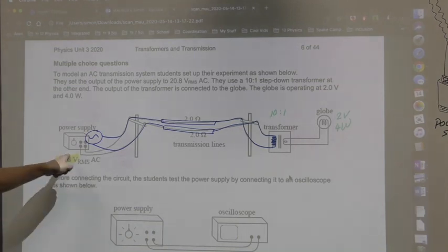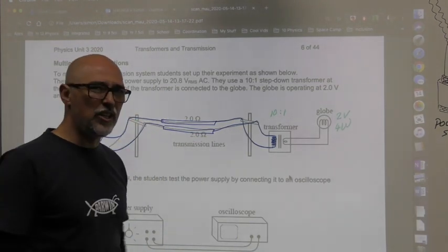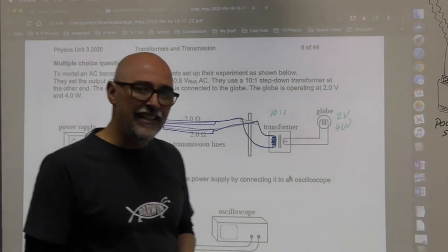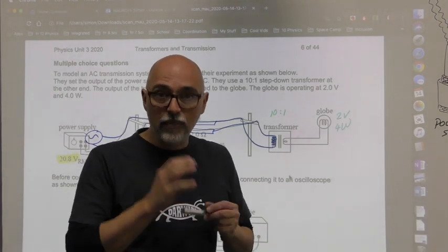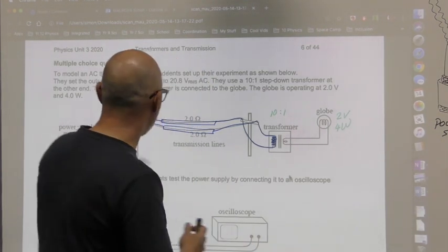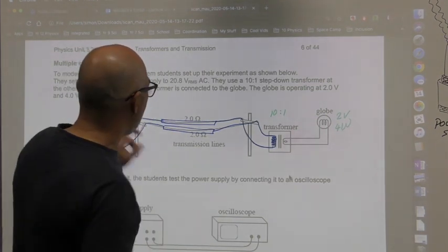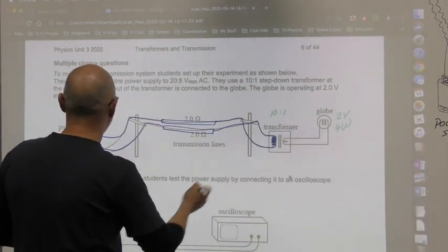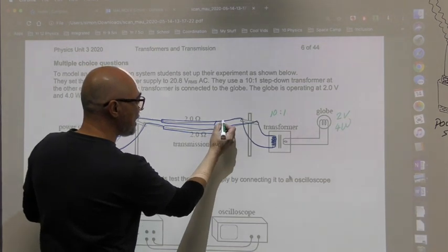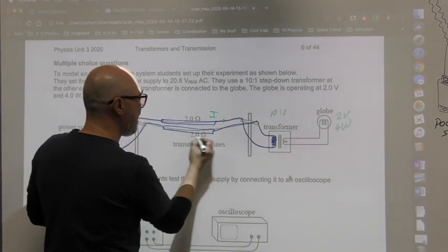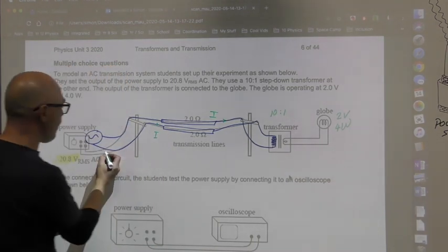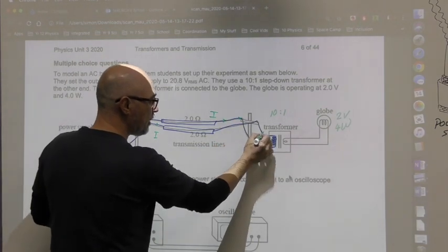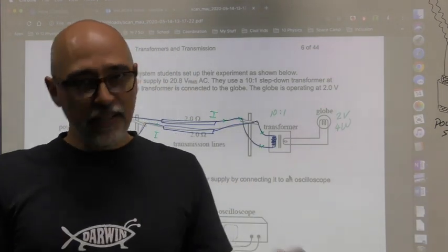So you've got a power supply, wires, and a couple of components here that will drop voltage over them. What you're looking at here is a series circuit. If you treat this whole section here as a series circuit, then it means that you know one really important thing: that the current in this line is the same everywhere. Anywhere I measure the current in this loop, it's the same. Why? Because it's a series circuit.